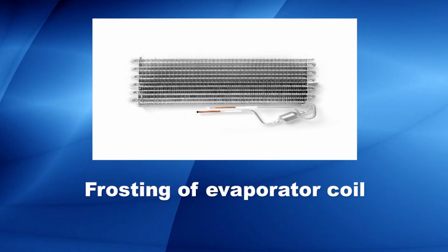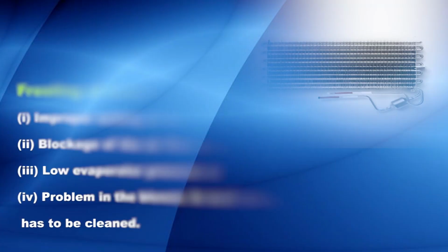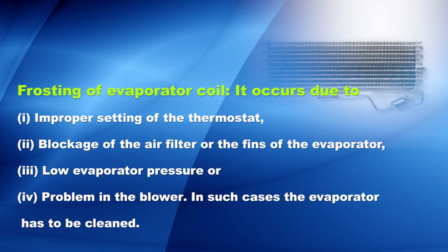Frosting of the evaporator coil. It occurs due to improper setting of the thermostat, blockage of the air filter or the fins of the evaporator, low evaporator pressure, or problem in the blower. In such cases, the evaporator has to be cleaned.